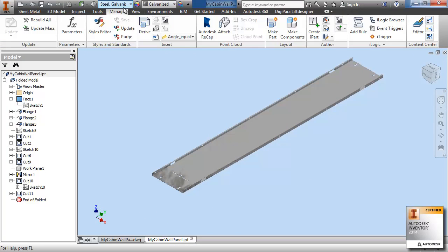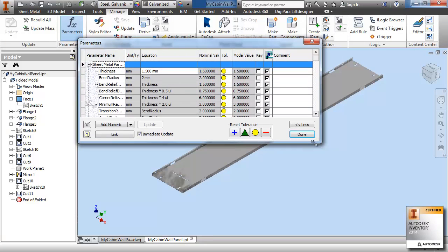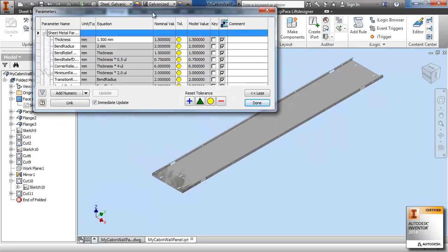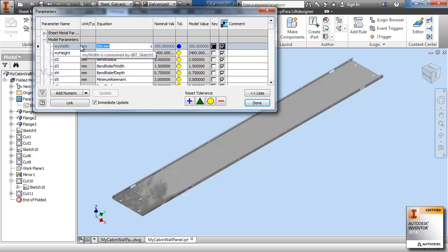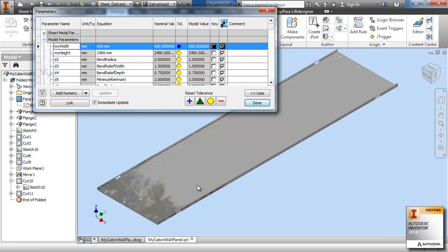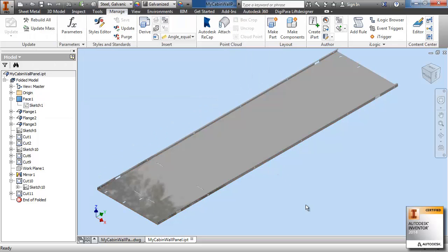And now if we try everything, manage parameters, let me resize that, make that smaller. We make it higher, 2400. You see there is a distance here between these two items. We should adapt this also. Let's put it 600 here. So it seems to work quite properly. Not every component is properly aligned, so this is not. So you see what you need to do. You need to justify all the things so that your component properly changes as you like for the different sizes.